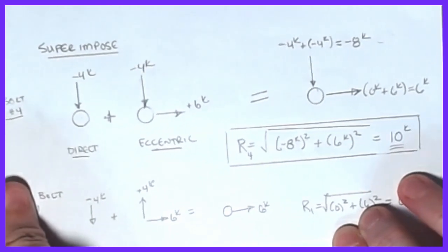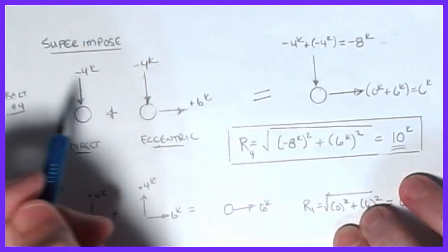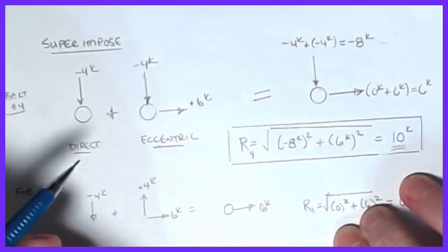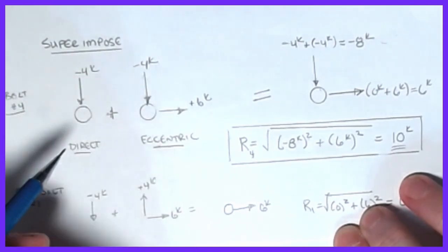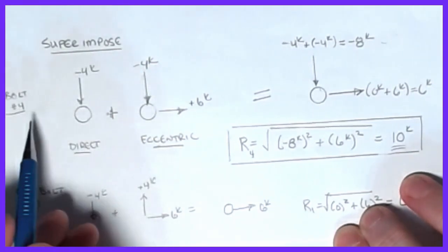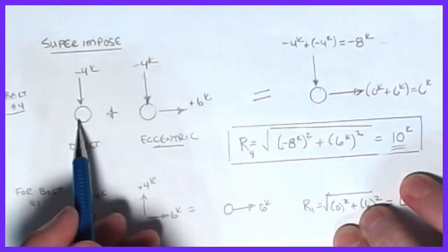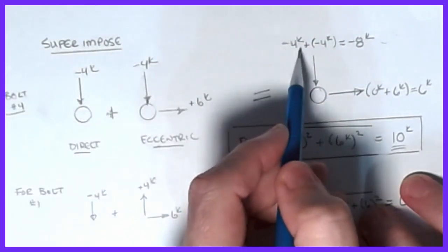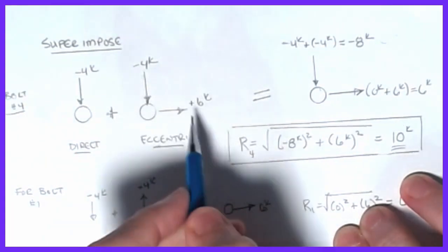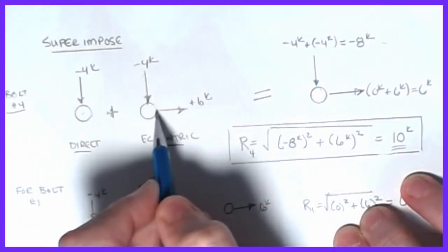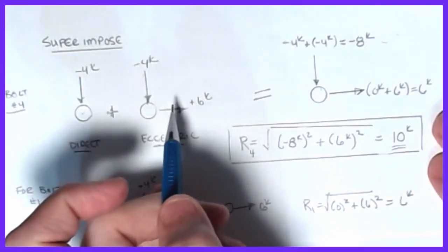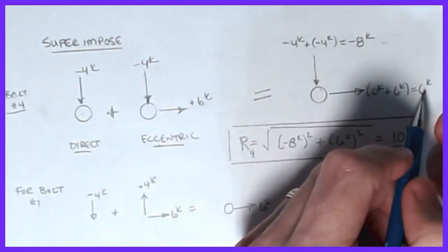So if I add all those together, and again, this is an elastic vector method, so we're still assuming linear elastic isotropic homogeneous behavior, that nothing is deforming locally, that everything is static and able to withstand the loads. And so for bolt 4, when I add these two together, I get a -4 plus another -4 gives me a total of -8. Then I take 0 on this guy plus 6 on that one gets me to +6. And so the total is -8 down and 6 to the right.